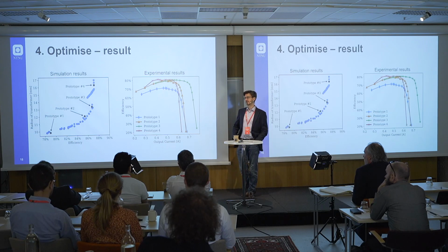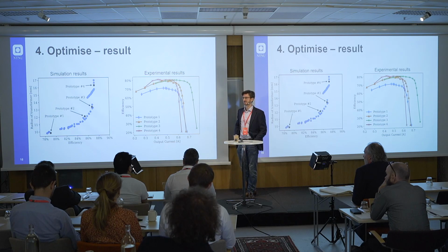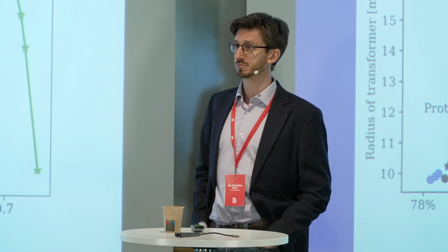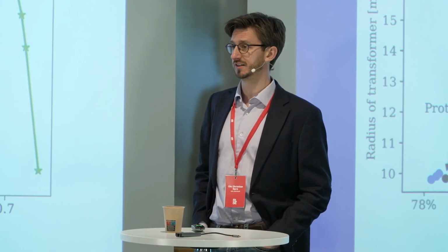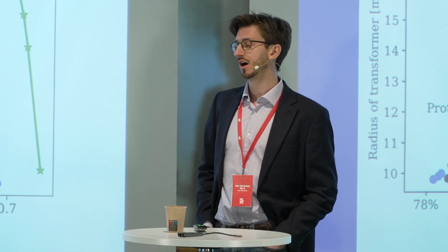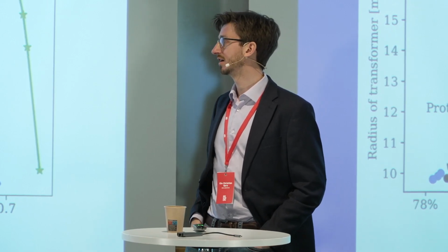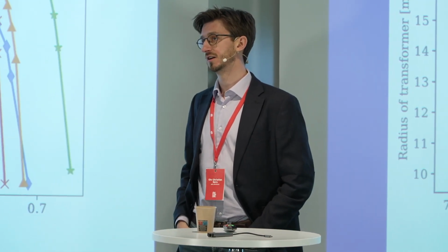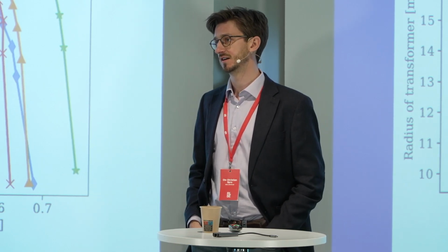A part of it is output capacitance losses, and then there's the nonlinear dynamic on-state resistance. We're operating at very high frequency. We're also operating the chip from Texas Instruments outside its data sheet, which stops at 5 megahertz, I think. But a lot of the losses are in the gallium nitride. Other than that, you could optimize the passives to have less resistance.